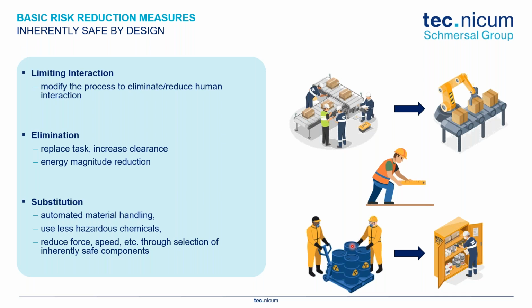Now, what I want to do is look at these individual guidance that they're providing from ANSI B11.0 and see how this can affect the risk factors. When we look at the risk factors, we're looking at the severity of injury, the exposure to these hazards that you have identified. We're looking at trying to be able to avoid the hazard.